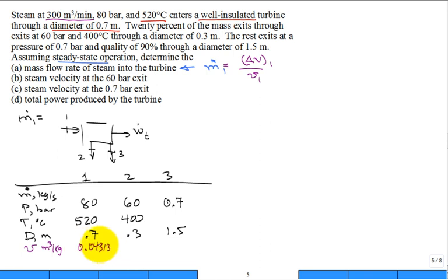0.04313 meters cubed per kilogram. Right. And then when I'm in the table and my finger's on that line, I suspect I'm going to need enthalpy in kilojoules per kilogram. I'll just read that off right away. 3447.7. Okay. Now that I have the specific volume, I can make that mass calculation.